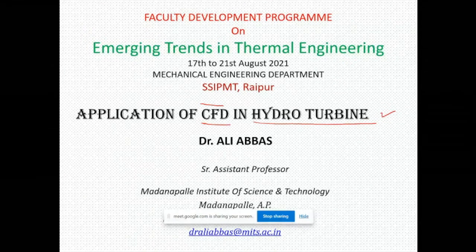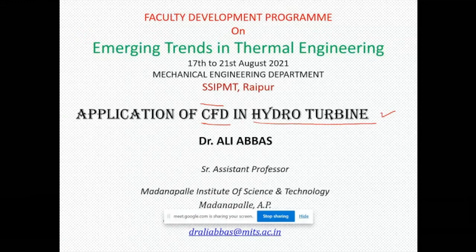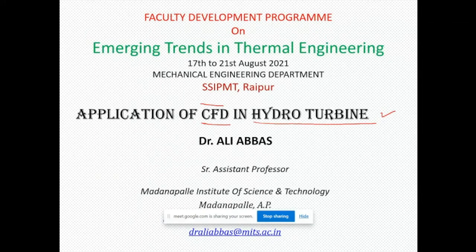There are various kinds of turbines to harness the potential at the level of micro and mini hydro schemes. Conventionally we use three kinds of turbines, Pelton, Kaplan and Francis, but unconventionally, for lower potential, we go for many other turbine technologies.